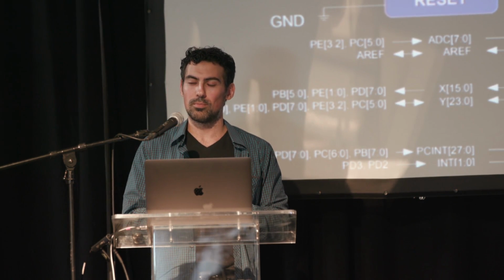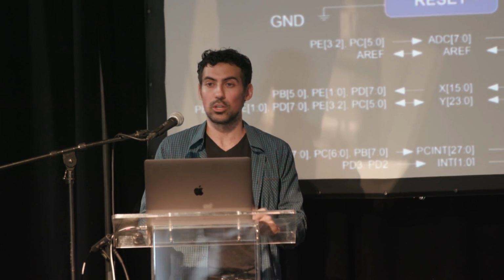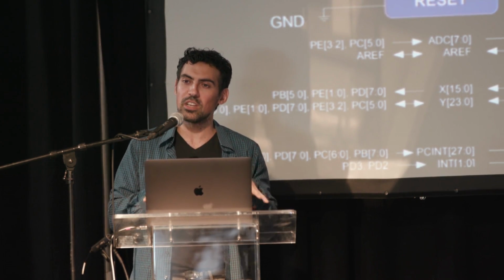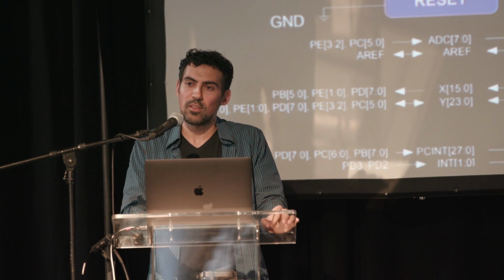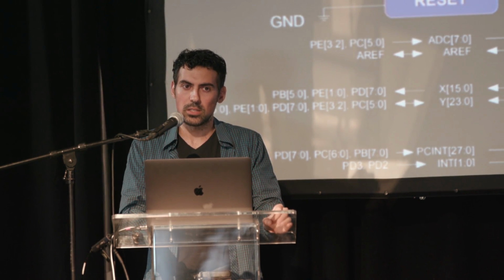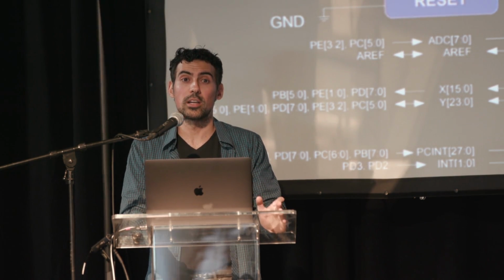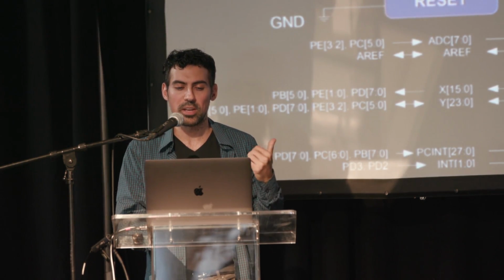Maybe you wanted to make rainbow tables instead of having UART or SPI or I2C or USB. All of these devices can be reconfigured to do really interesting things. And the nice thing with FPGAs when performing these types of attacks is that you get an extremely precise clock. So when you're trying to do very precise attacks, the FPGA will be very beneficial.